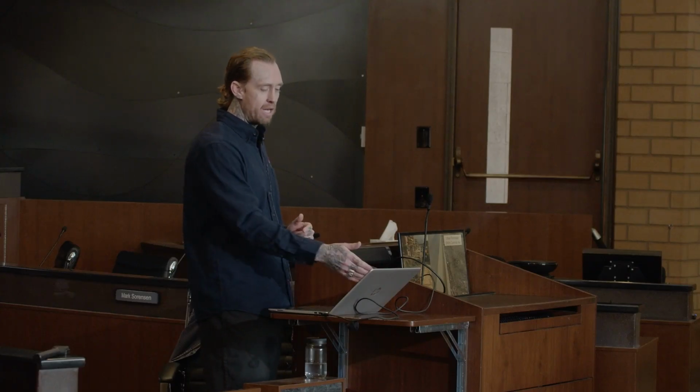Of course, they didn't want to do it. And they're just tracking tons of sediment out onto the sidewalk, which of course I ended up having to take a sample that day because it had just rained and the gutter was full of sediment and water, and they got charged a nice sample fee when they could have just kept that perimeter control in place. So this is clearly a terrible perimeter control here that is not being implemented properly.